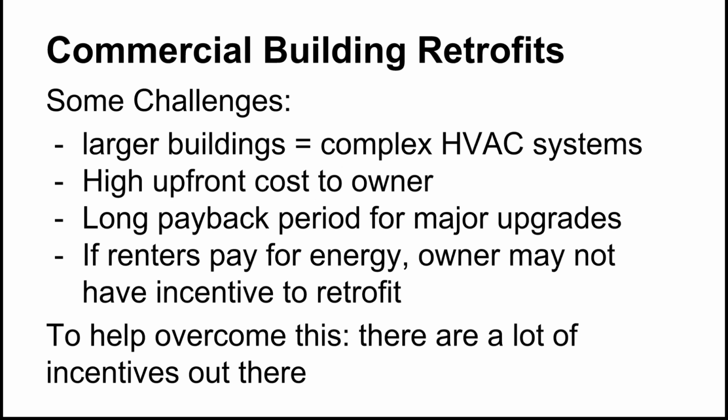Okay, so some of the challenges with commercial building retrofits, one is that these are really large buildings. They have very complex HVAC systems. Basically, the bigger you get, the more complex they get, and especially when you're thinking of things like hospitals, you have areas where you're containing people that have communicable diseases, so you have to be really careful with the building pressure. You want negative pressure within the room so that air is being sucked into that room, not being pushed out.